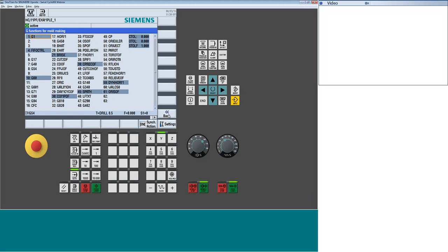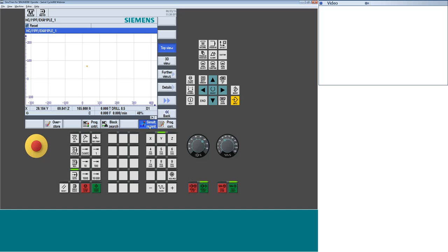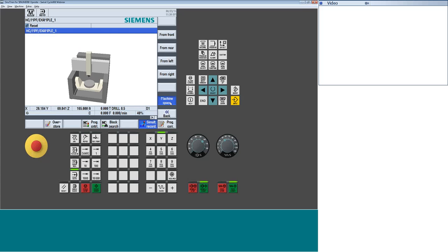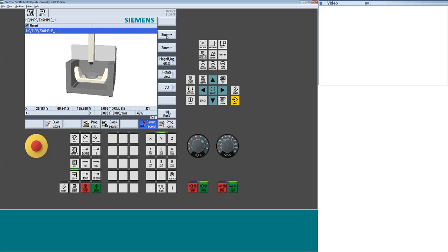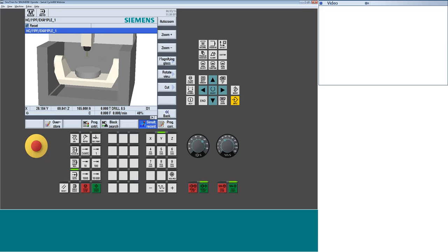Now, the one thing I do want to show you here, and we can play around with our simultaneous record, and we can go into our machine space model, is what the motion of the machine would actually look like. So if I zoom in a little bit, this is going to show me, as I run it, what the actual motion is. So there's your 9 degrees, right? There we're machine up the plane. So it just tipped the table just a little bit, just enough.